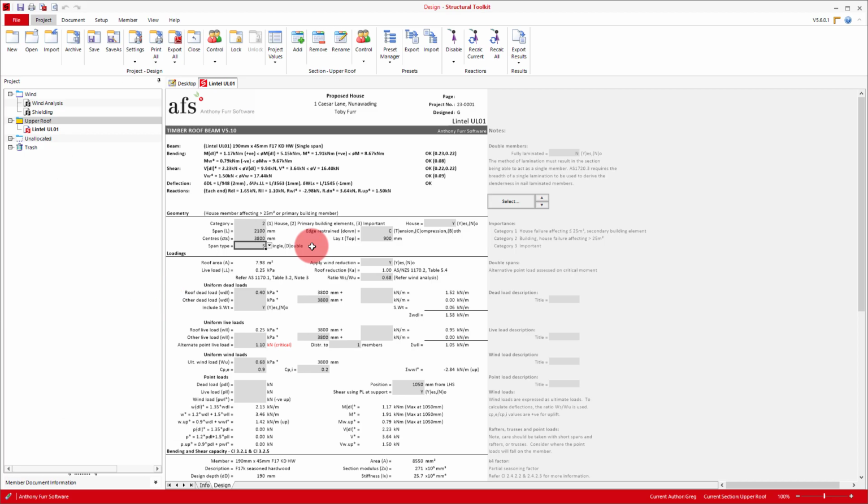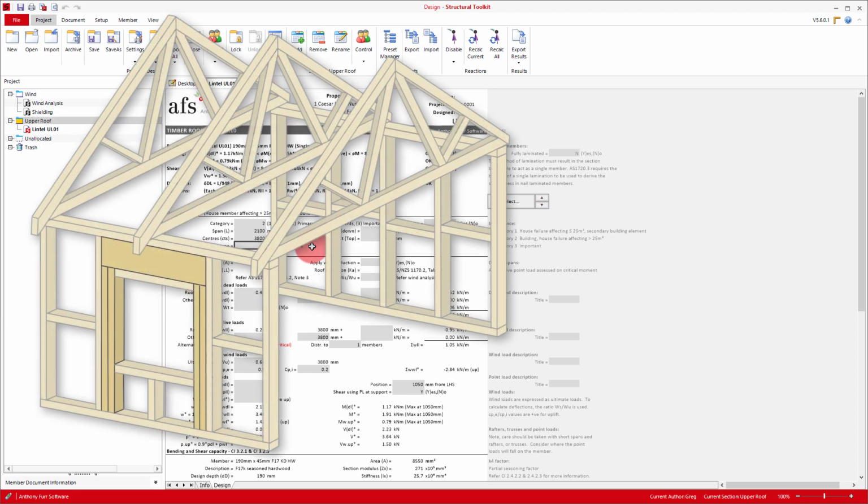It's probably worth mentioning here that although technically the trusses themselves are going to apply point loads at 900mm centres along the beam, providing the beam is long enough, idealising it into a UDL is much more convenient. We'll look at this more with a shorter lintel.